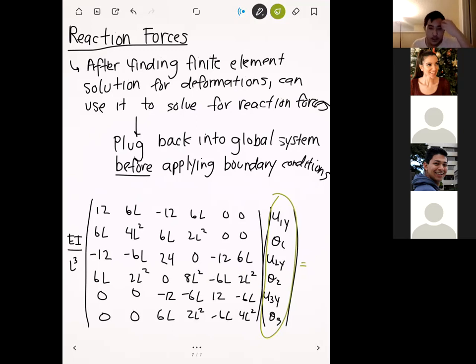Again, with these kinds of complex and tedious matrix calculations, don't be afraid to use MATLAB, because that's what MATLAB was built for. If you can perform this matrix vector multiplication in MATLAB, that's going to help you out a lot. Just like we did before, after you compute these forces, it's usually good to perform a quick sanity check. You should check to see whether some entries are 0 or not. Generally, you should get values that are non-zero in 2 situations.